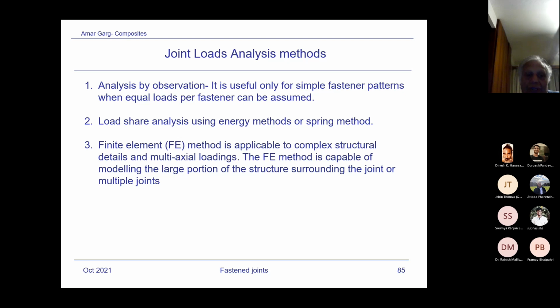So we use the load share analysis, and the load share analysis has been developed. The software is available at Boeing, of course, and they use various methods, two-dimensional joints and single one-dimensional joints with thermal effect, strap thickness, diameter, fasteners, fastener type, stiffness, because they are based on the spring action.